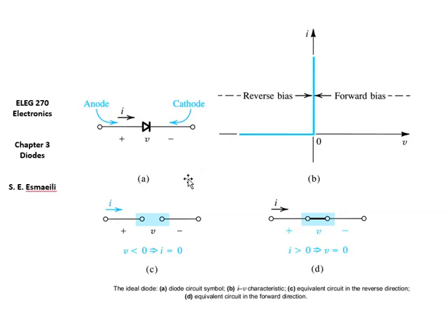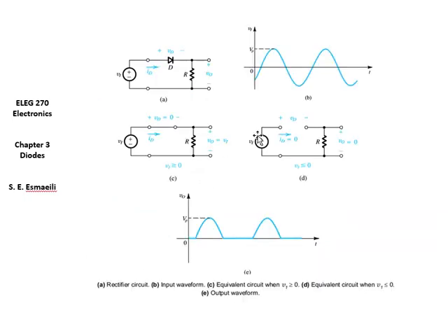As far as we're concerned, in an ideal diode, if you apply the voltage from the positive side, it will pass the signal towards the arrow direction. If you apply it on the negative side, it's not going to pass. That's why it makes the diode a very good candidate to create rectifiers. Look, if you apply a sinusoidal wave to a diode in a circuit like this, only positive cycles can pass. So that's why your output is gonna look like this.